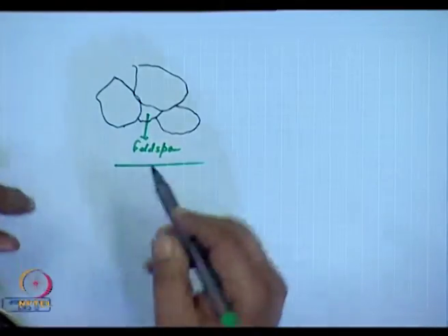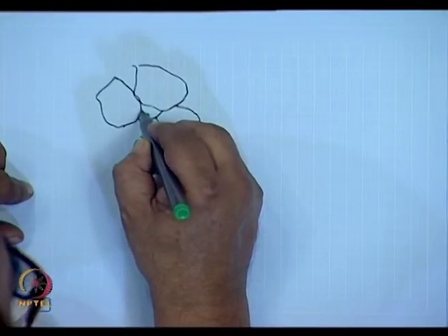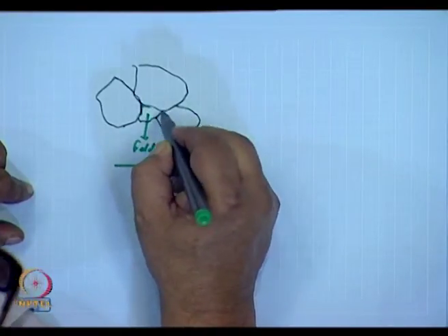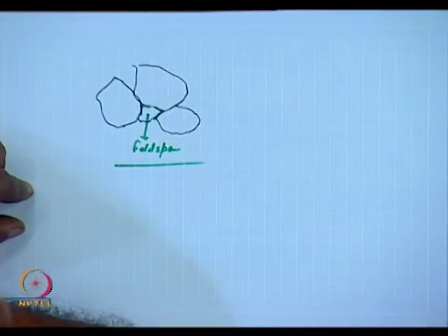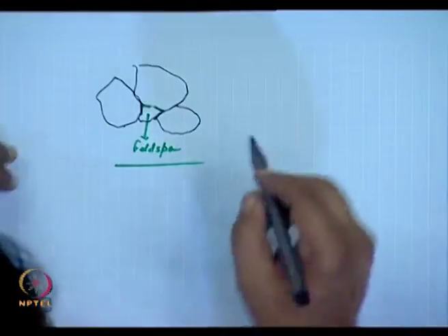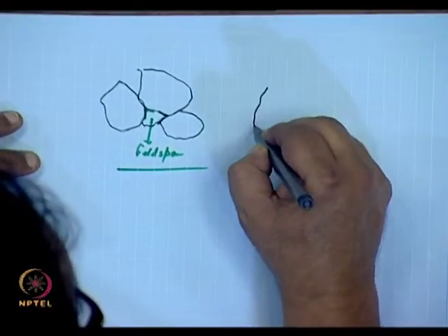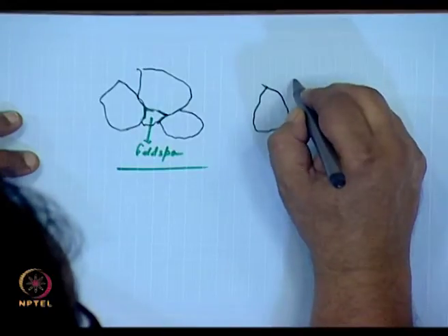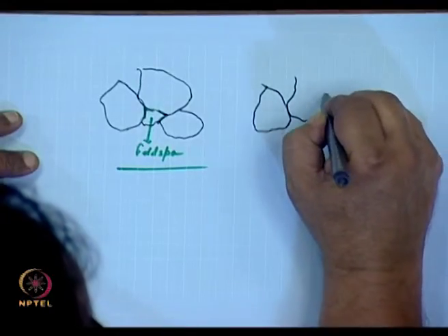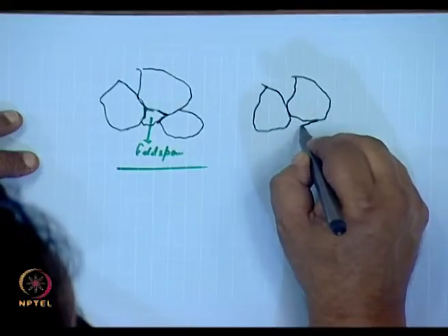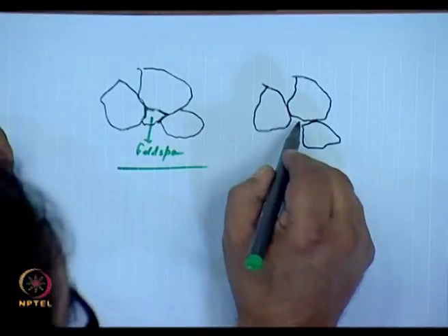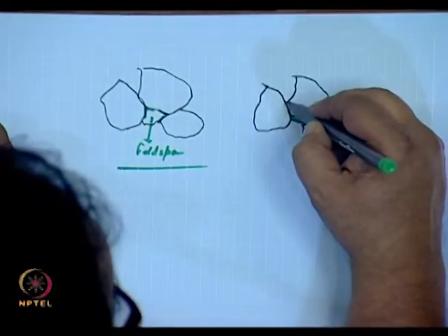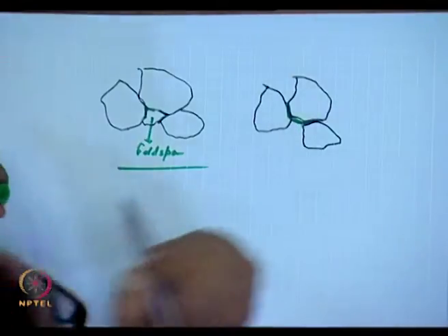As a very first step, this feldspar will melt. As the feldspar melts, this particular grain starts wetting the surfaces over here. It will wet this surface, it will wet this surface over here. What happens next? Now, I don't think I am that good an artist to have exactly the same size of the diagram I had drawn, though I will strive. Okay, it looks almost similar. I have got the feldspar forming a low melting liquid. It is spreading over here, it is spreading over here.